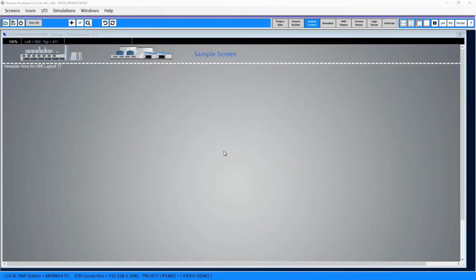This commands tutorial will describe the steps that you need to follow to send controls to remote devices. Most of these controls will be sent via the graphical icons on the screens, but you can also set the value of internal user-defined indications this way, and we will show you the benefits of doing this later in the video. To begin this tutorial, we will navigate to the Open Shipping screen in Display Creator.